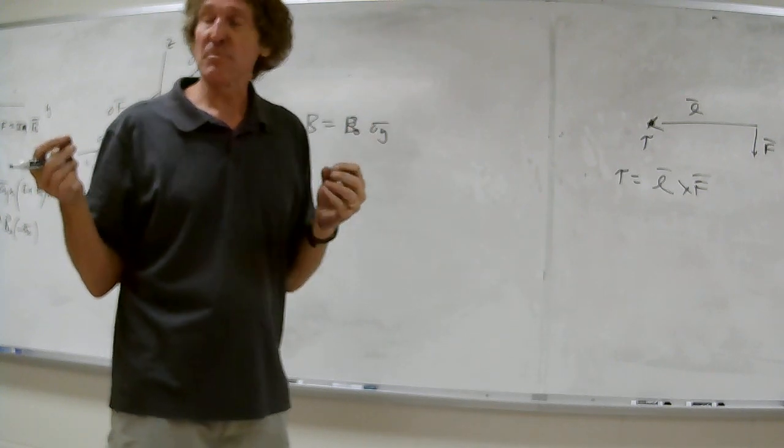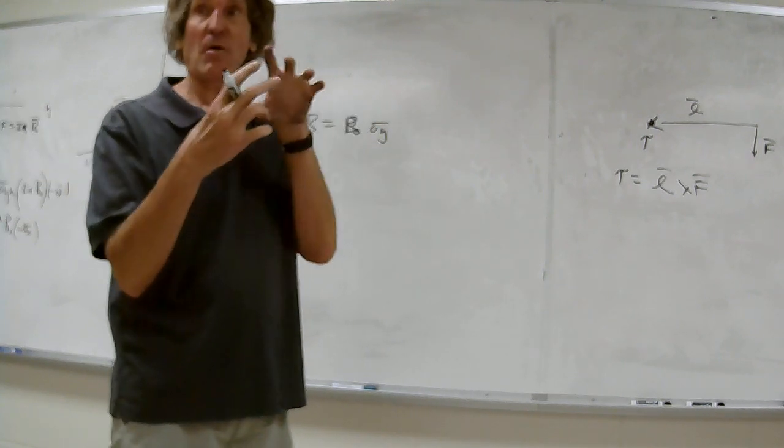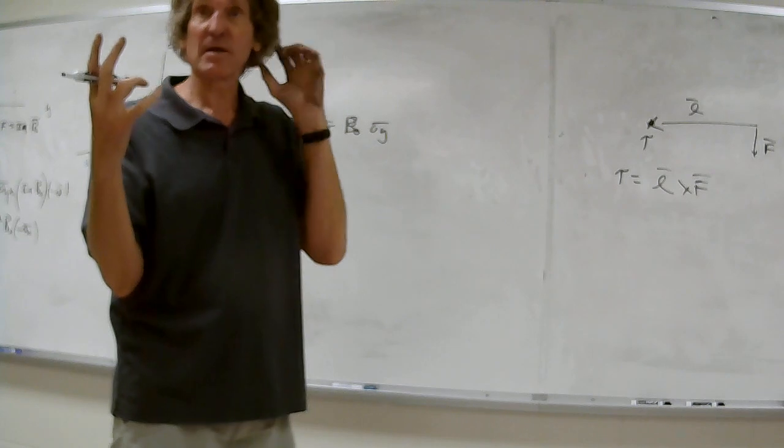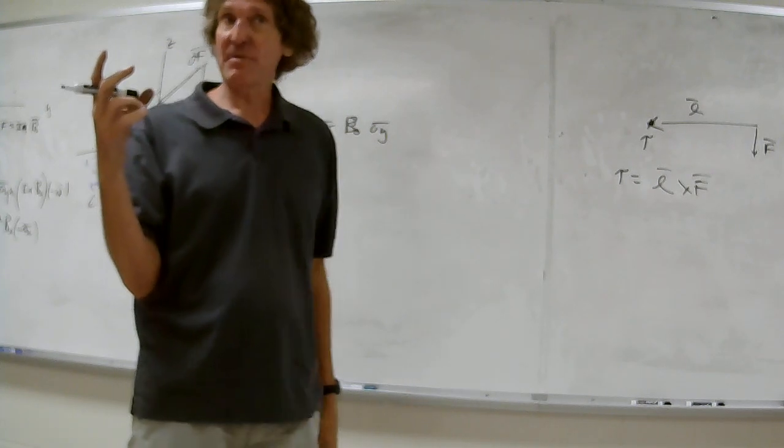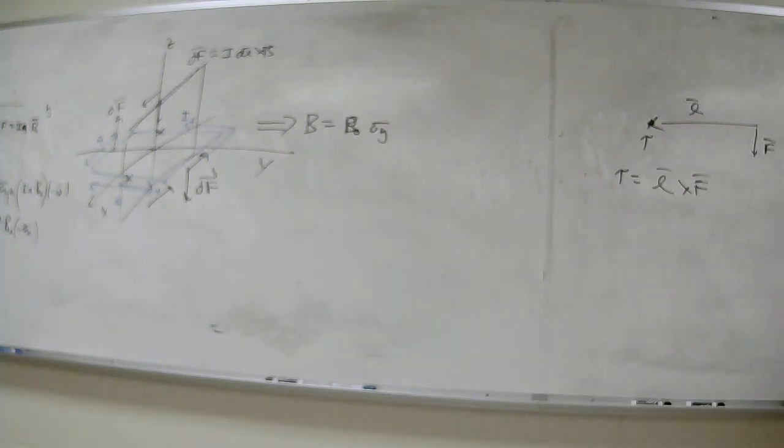Either the bearings will burn out and force it to stop, or the inside part, the rotor, will just blow up like a grenade. I've never seen it happen. I don't want to, but I know it does happen. It's a dangerous thing. So if you have DC motors, make sure you always have a load on it. There's probably a fail-safe so you can't run without a load, but I don't know enough about that.